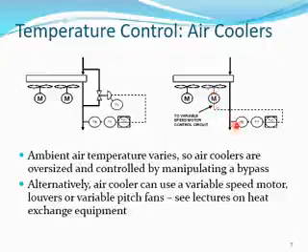For example, if the temperature here goes increased above the set point, we have to increase the rotation of the motor. It gives a signal to the motor to run to increase the RPM in order to cool down, in order to reduce this temperature. And contrawise, if the temperature here goes below the set point, this motor will be stopped or its speed will be reduced.